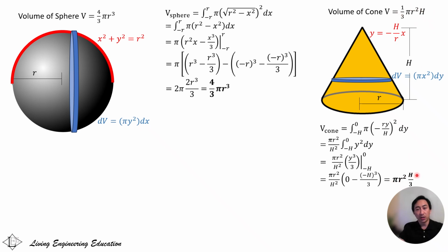Now, one thing to notice is when you have a triangle or a cone or anything shaped like this, 1/3 or 2/3, depending on which direction you're looking at, comes up over and over. What this represents is if you look at a triangle and you're trying to find the center of mass of the cone, it's 1/3 of the way up here, right? If it was a rectangular prism, it'll be halfway. You see it's bottom heavy down here, so it does make sense that it'll be closer to the bottom than it would be at the top, and below the halfway point, right? So this 1/3 point shows up a lot.